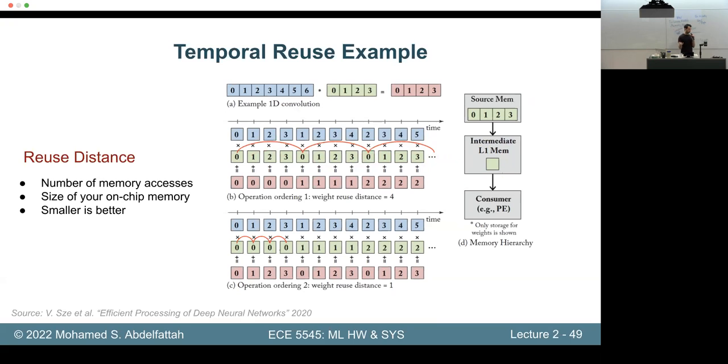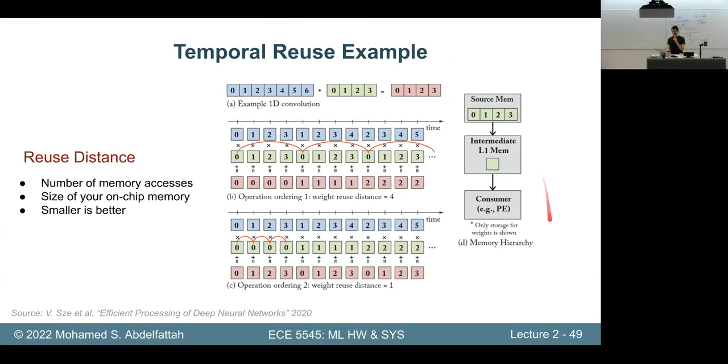So as people correctly pointed out, it's either a cost of refetching that data because I need to dump it back to a cache or some scratchpad or some on-chip buffer, or I would need to design my hardware such that it has a larger number of registers close to my PE to be able to cache like 4 operands at the same time to do my computation. So basically it's bad in one of 2 ways.